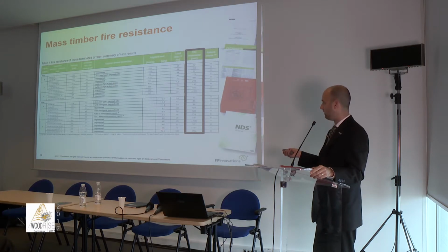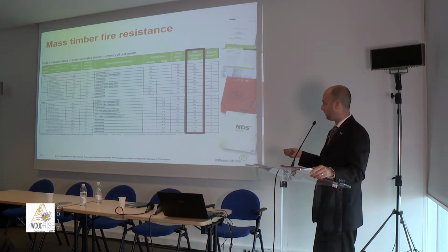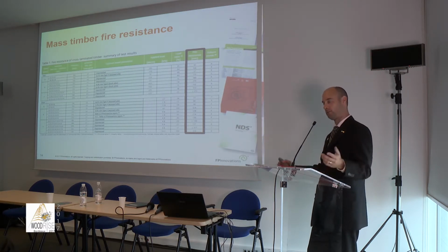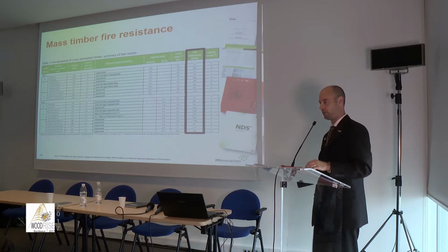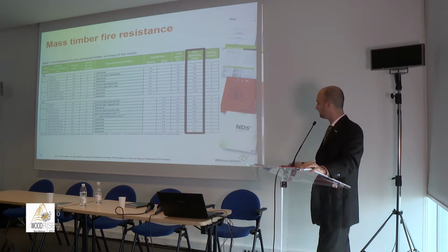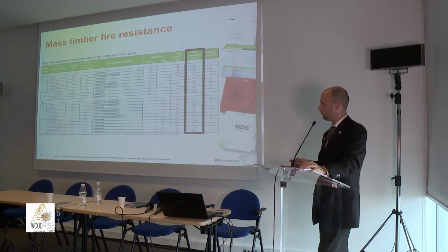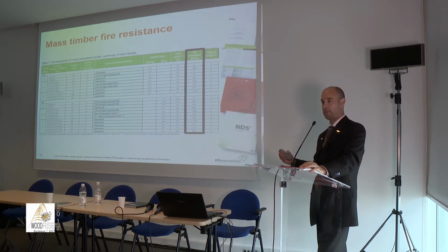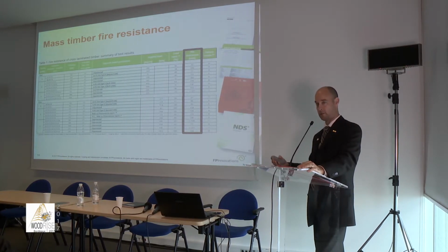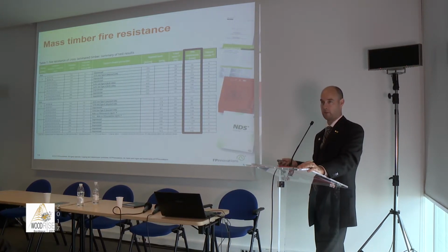And we also have, for example, floors that were loaded at 100% of their capacity, and we reached 178 minutes. So technically not a 3-hour test, but within 2 minutes of it, it's essentially a 3-hour fire resistance. So really, to fulfill the needs for higher, taller buildings that need greater fire resistance, it can easily be achieved, although it's wood.